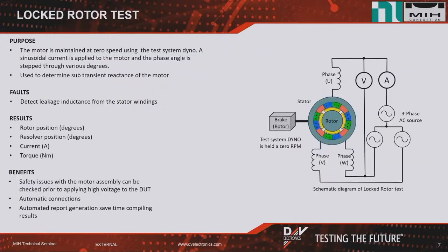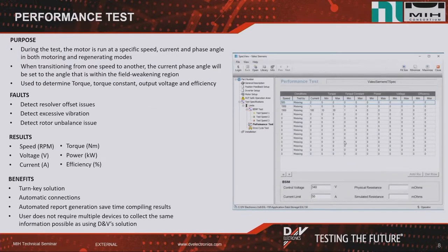Moving on to things like a locked rotor test so that you can start looking at the subtransient reactances. Again, verifying design behavior, and also looking at this for subsequent use if needed for controls development or controls tuning as well.